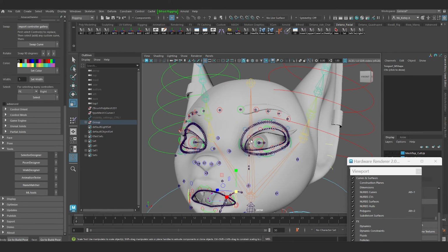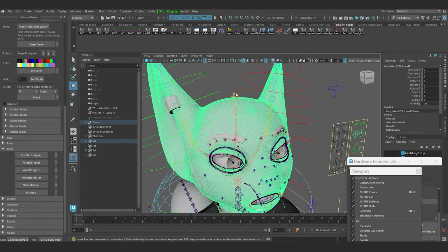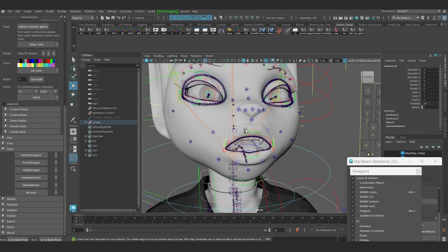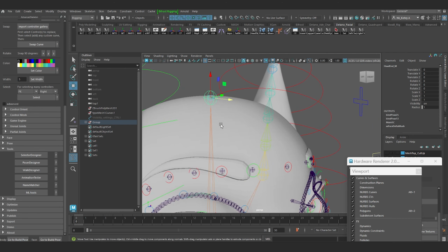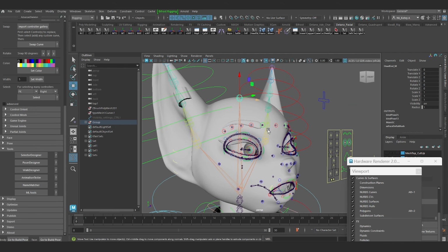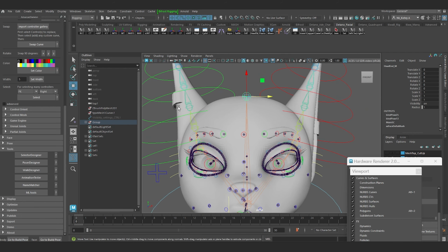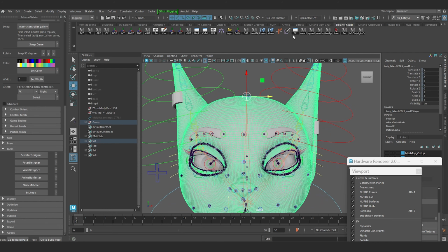So let's get going. One thing I want to do is this head end joint is part of my skinning, and it's impacting some of my weights, and it really doesn't need to. It's not supposed to be in here. It's supposed to have 0 weighting. Now, to avoid it getting any weights after I take assignment away from anyone else, I'm going to take this away from the skinning.